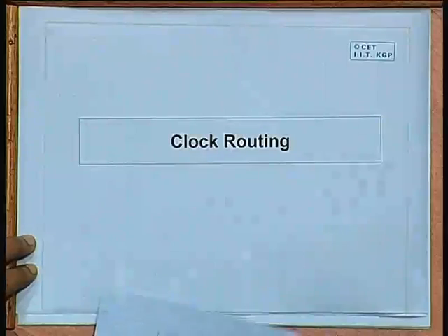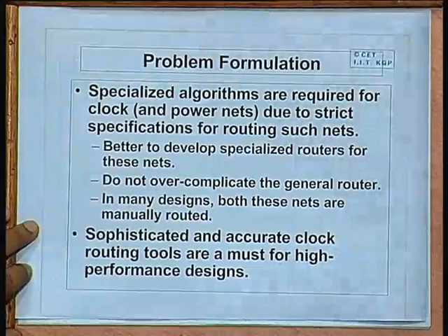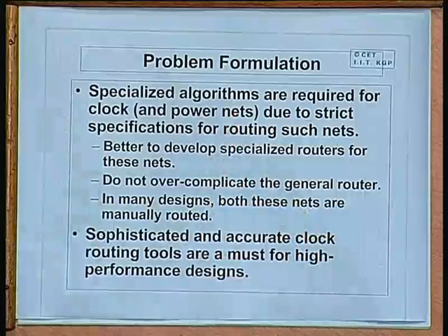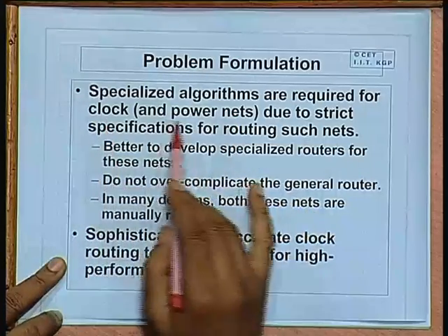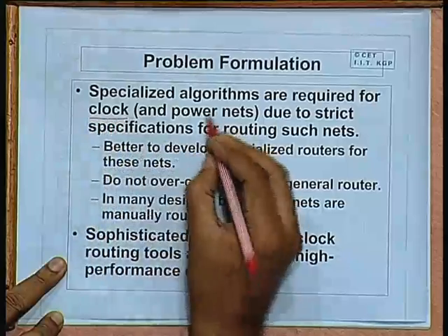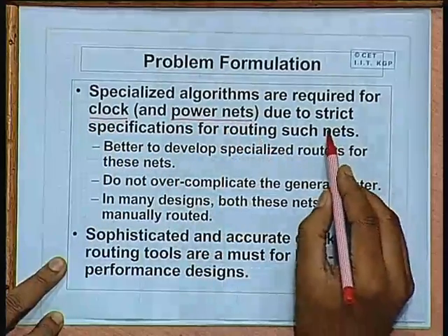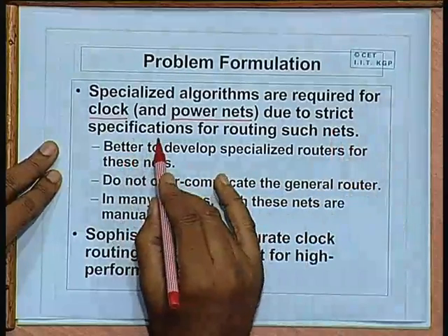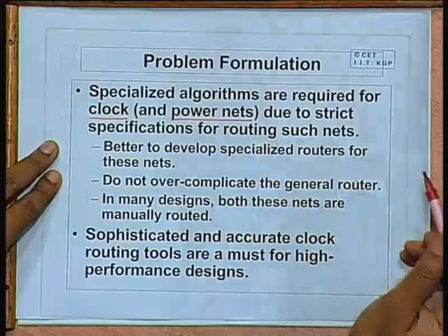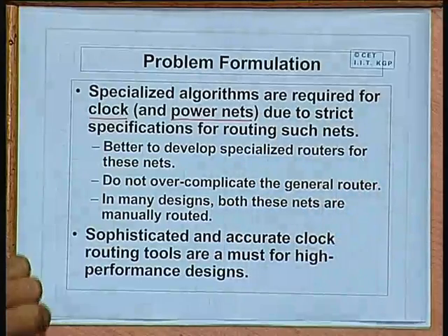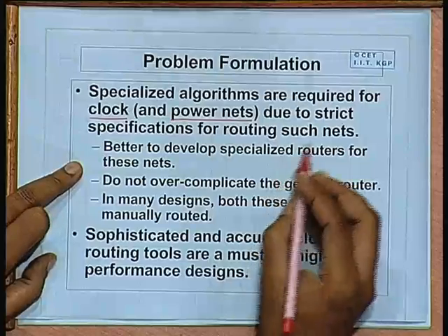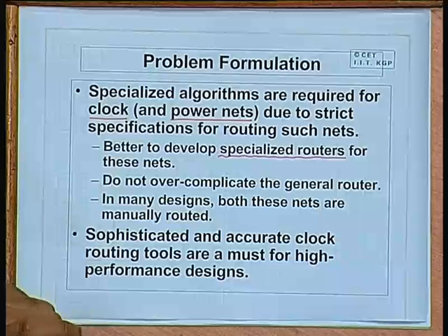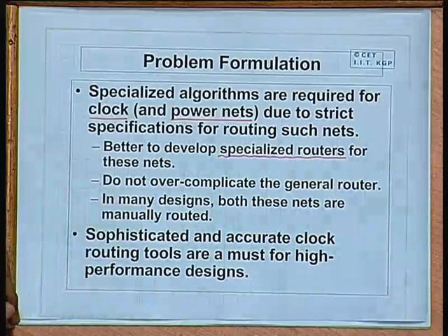Now, in clock routing, in terms of the problem formulation, I am just repeating, we need special algorithms to route these nets. We are talking about clock, and we shall subsequently be talking about the power nets as well. They are important and they need specialized algorithms because there are some strict specifications which are often different as compared to conventional signal nets. So, for these kinds of nets, people have developed special purpose routers so as to meet their individual requirements.